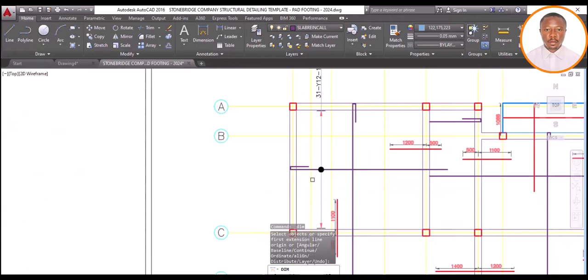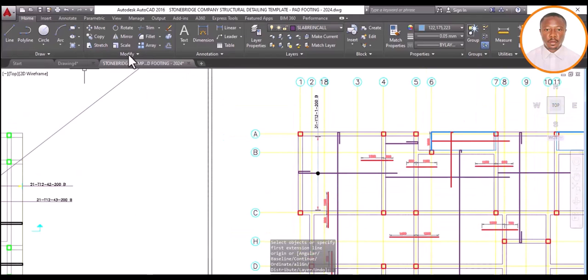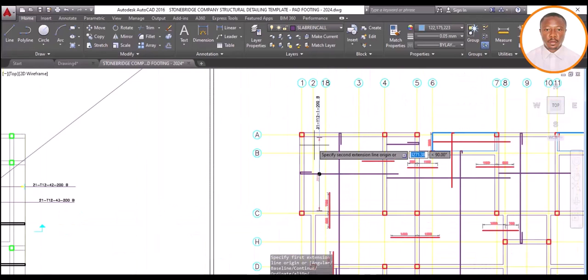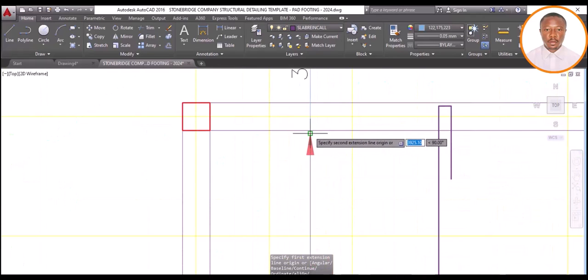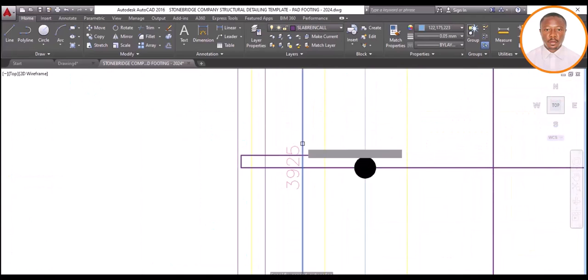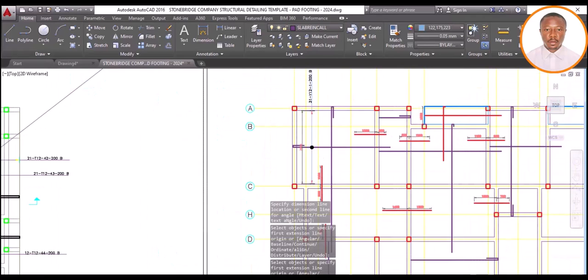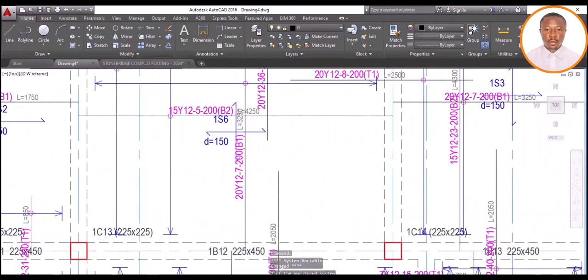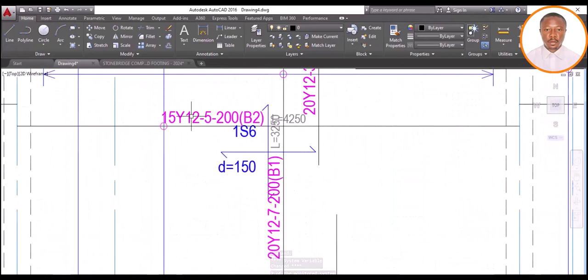Now you discover that during our form work, we only have a space of 225. So my rebar starts from here. That's my indicator to this place. So what's our total length? Is what? 3,925. Good. And when we go to our Prokon structure, you will notice that what's our spacing is what? At 200, isn't it? At 200.